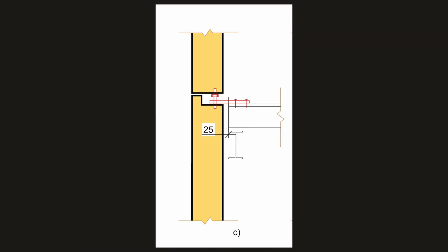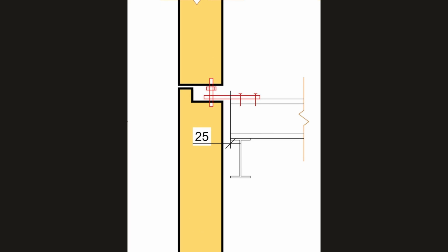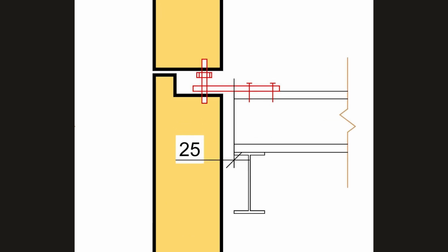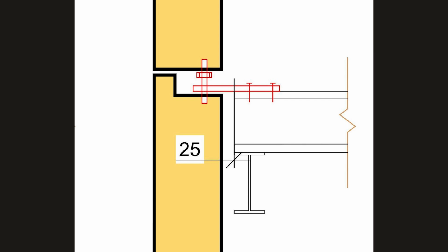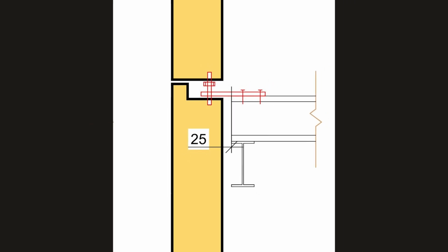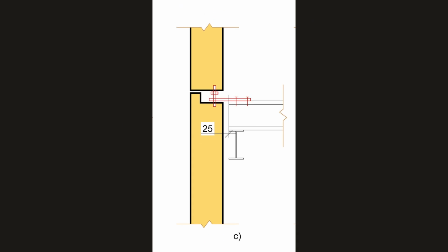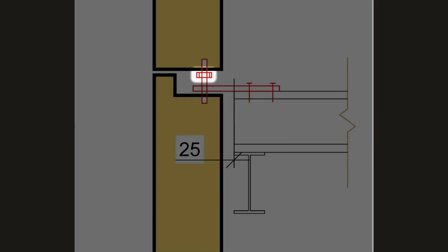In the case of a solution where the facade is located in front of the intermediate floor, a steel plate, threaded rod and a support bracket with nuts are installed on the intermediate floor. The lower facade element is attached from the top edge with a mounting bracket. A corresponding hole is drilled in the element's wooden beam for this purpose. The upper element is then lifted onto the threaded rod. The height and mutual placing of the elements are adjusted with adjustment nuts.